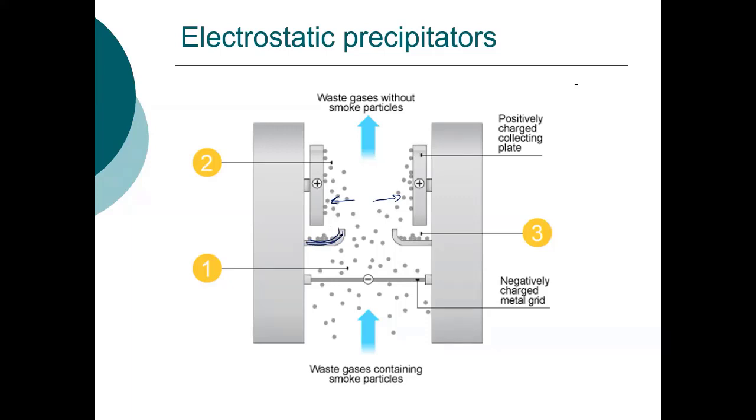And then what happens is you shake, or rap, these plates. That causes the particles to fall into a hopper, and then they can be collected and either treated, disposed of, or reused. And then you've got clean air coming out the top.